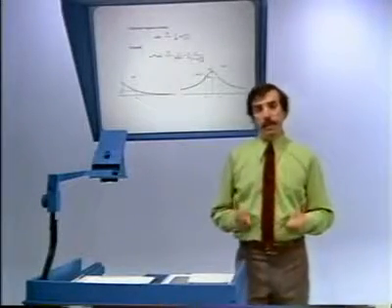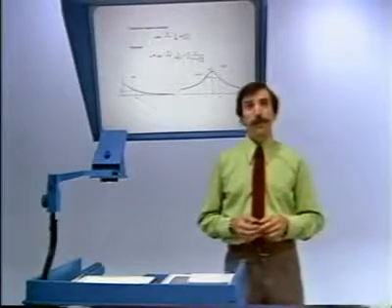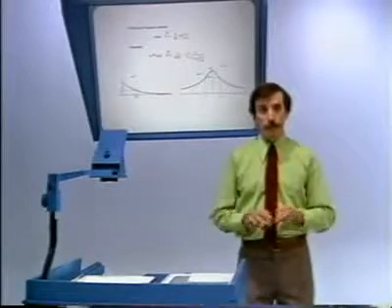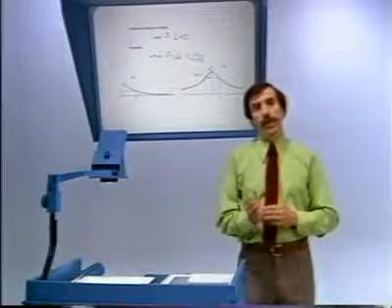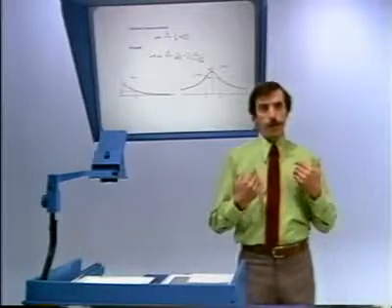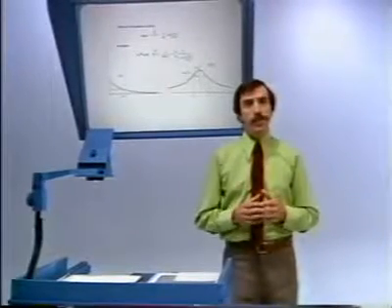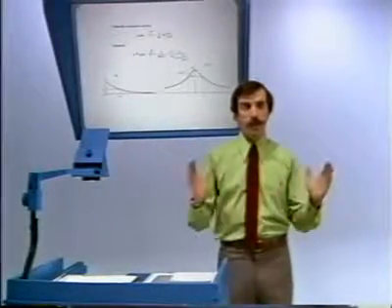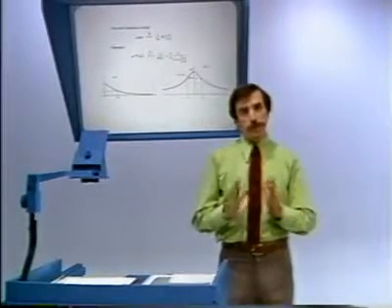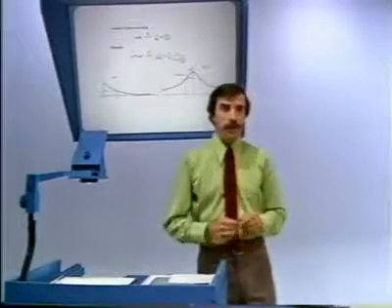Now, this, in fact, is probably a result that you're already possibly familiar with in somewhat of a different context. Essentially, you can think of this as a generalization of the notion that if I had a signal that was recorded on a tape player, and I played the tape back at, let's say, twice the speed, which means that I'm compressing the time axis linearly by a factor of 2, then what happens is that the frequencies that we observe get pushed up by a factor of 2. And in fact, let me illustrate that.